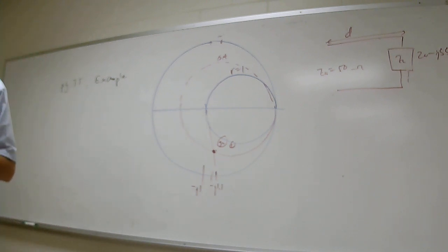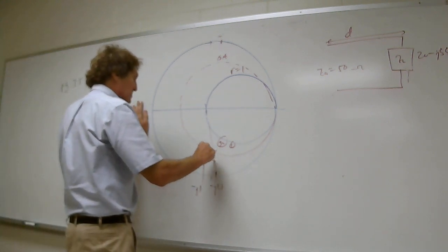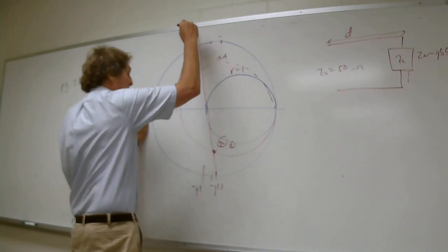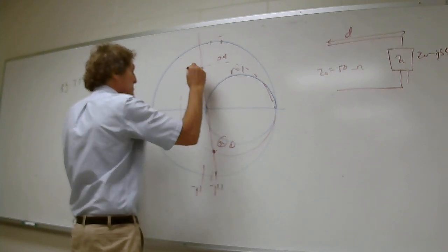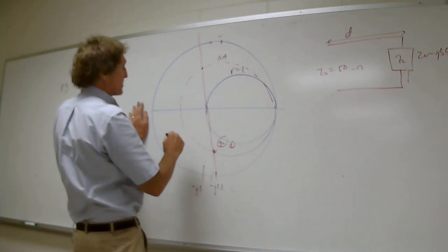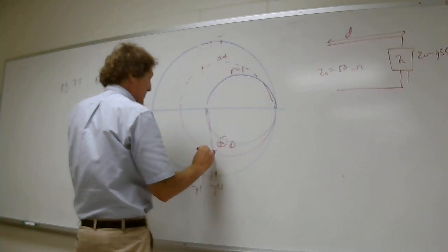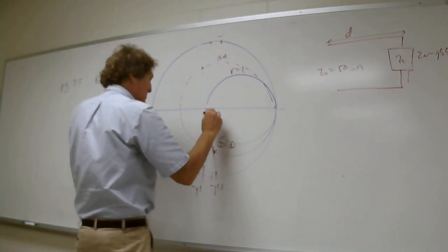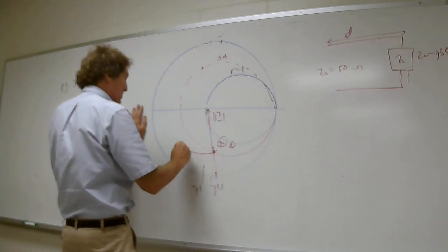This next part's real important. We're not going to do this using impedances. We're going to use admittances. Y'all hear me? Admittances. Take two ways to do this. Take your line, go straight through the center, and where this straight line intersects the circle you drew, you should have drawn, oh, I didn't even draw the circle. I got to draw the circle. From here to here, this should be your reflection coefficient magnitude at the load. And then you need to take your compass and draw a circle.